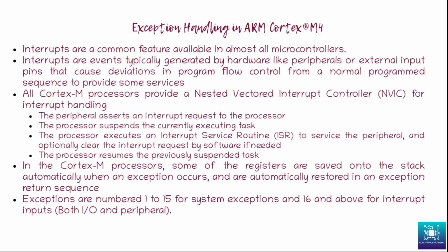Now, in Cortex-M processors, some of the registers are saved on the stack when an exception occurs. This is a very important feature of this particular architecture, that some registers are saved onto the stack automatically and they are restored automatically as well. This essentially means that it sheds the burden of the programmer to save these registers on their own.